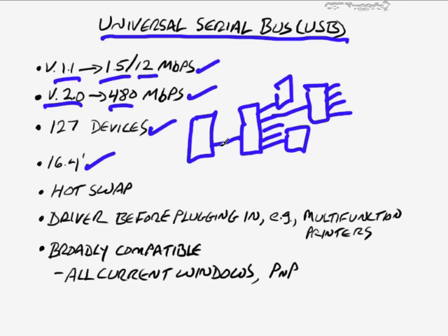If they're non-powered, then they depend upon power from the originating USB port back here. So if this is a non-powered one, and I've got another hub out here that has to supply power to devices, then you probably need to power this one in order to be able to supply power out here. Otherwise, you're extending too great a distance for that USB power to be able to extend out. Sometimes you can also cheat this as well.